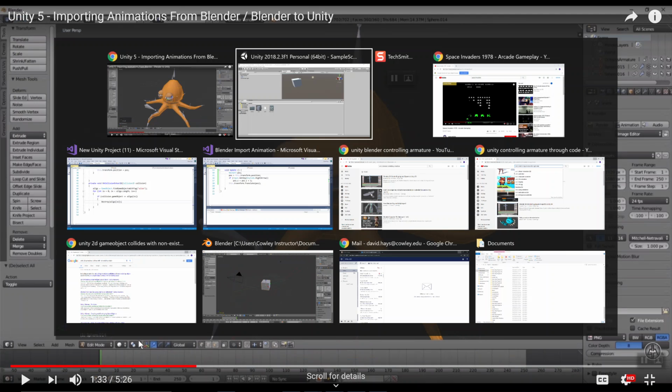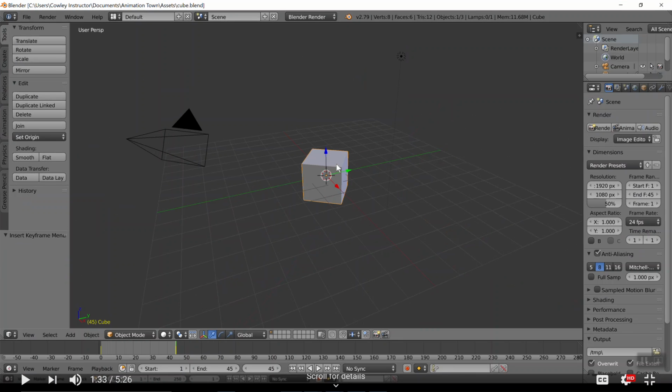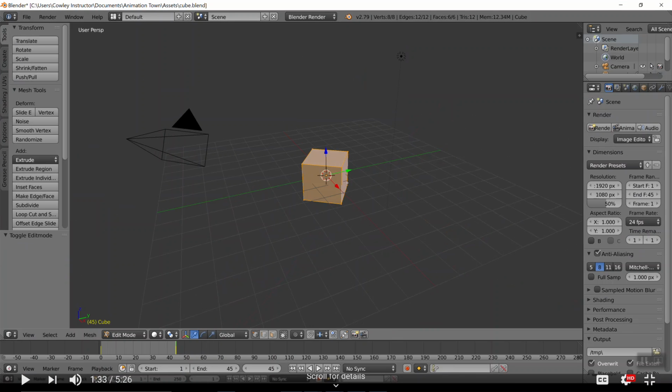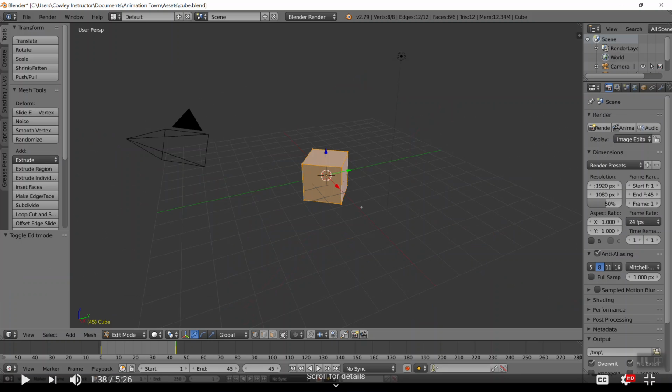Okay, so over in Blender, go into edit mode, so do a Tab. Everything's already selected on my cube. And cursor to selected. So Shift S, cursor to selected.